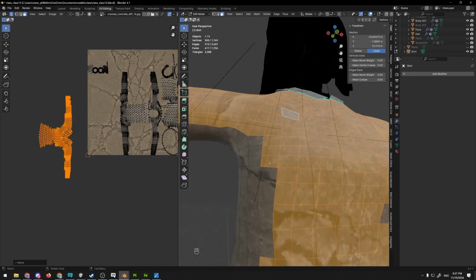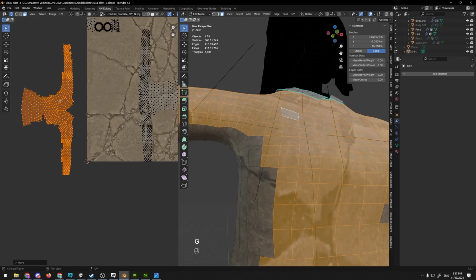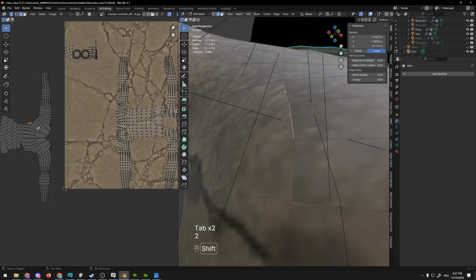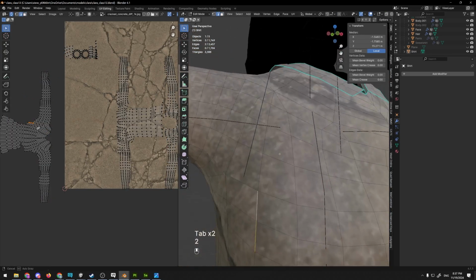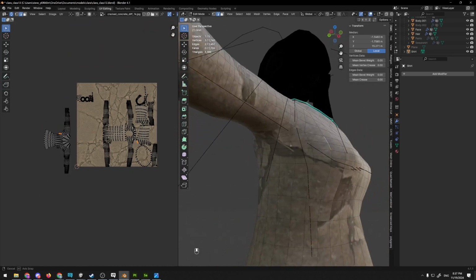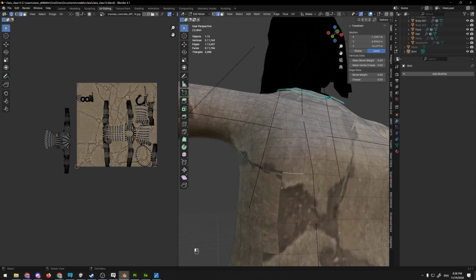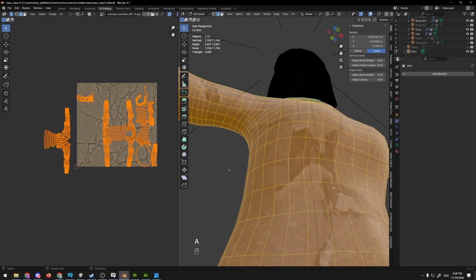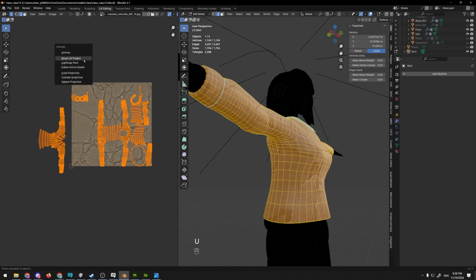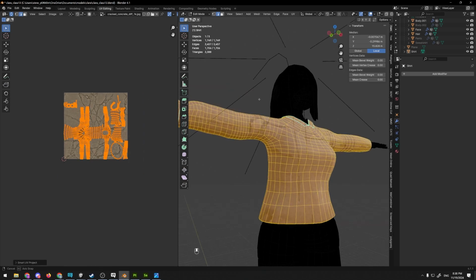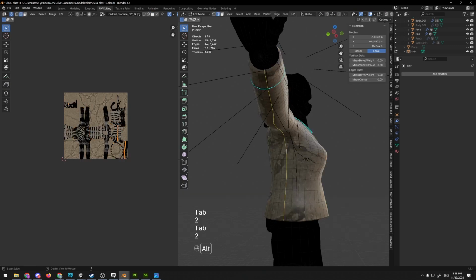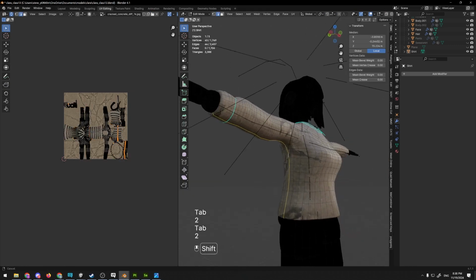But you're going to see a lot of weirdness in this texture along seams. So you'll notice how this line right here doesn't blend. I mean, there's a completely different texture on one side of it than the other. Using this kind of monochromatic texture doesn't make that obvious, but you can see along the seam, right? It doesn't connect. To fix that, we want to use better seams on our UVs. So Smart UV Project is not going to work very well. To actually create good UVs, we need to create seams on our object along edges we actually want to make islands out of.